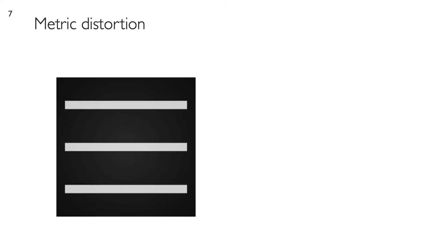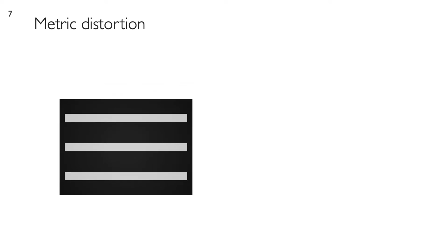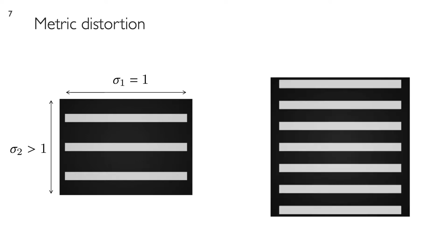When we release the textile, we can see that along the ribbons, the shape is still as wide as before, because the plastic resists deformation. And we say there is a distortion, a ratio of lengths equal to 1. In the perpendicular direction, however, there is a larger amount of distortion. What's interesting is that this amount can actually be controlled by controlling the density of ribbons. If there are more ribbons on this square, the distortion will be lower.